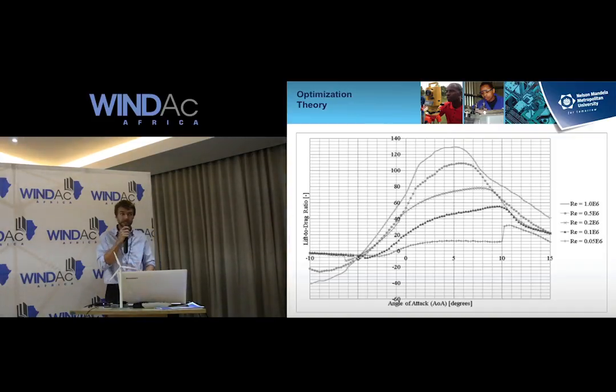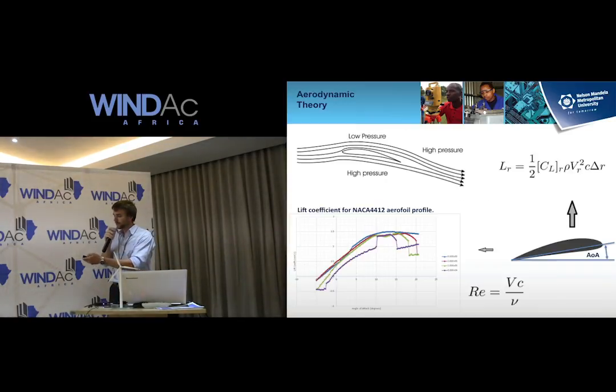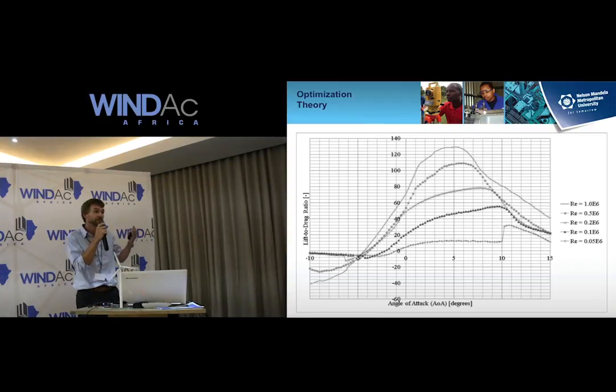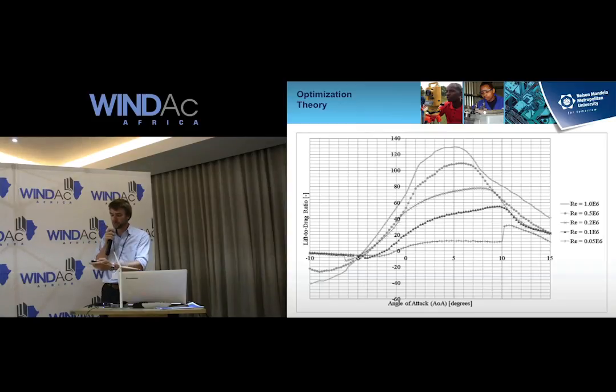And so there is kind of your optimization process conventionally for a wind turbine. You want to, if I go back one step, your lift force here is good. If you think on an airplane, you want lift, you don't want drag. Okay, so the ratio of your lift to drag components, you want as high as possible, as much lift for as little drag, and that's what you're aiming at. So the same thing applies for wind turbines.